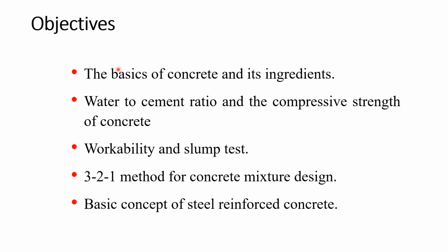From this experiment, you will learn the basics of concrete and its ingredients. You will learn the water-cement ratio and how it relates to the compressive strength of concrete. You will learn workability as the most important fresh property of concrete and how to use a slump test to measure workability. You will learn the 3-to-1 method for a quick and easy concrete mixture design. You will also learn the basic concept of steel reinforced concrete.